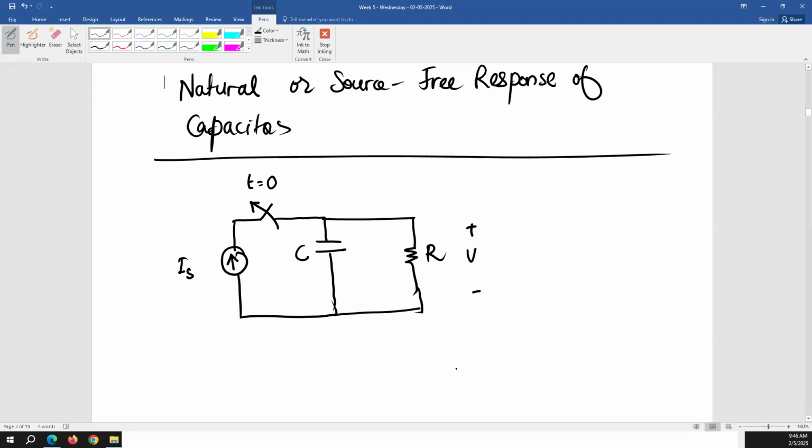So when we are analyzing these types of circuits, the first thing that we analyze, based upon the description that is given to you, is how long the circuit is running. If it is given that the circuit is running for a very long amount of time, basically that is to tell you that the capacitor is fully charged. And the first thing you are going to do is find what is the voltage across the capacitor when it is fully charged. That becomes your initial voltage on the capacitor that you are going to use when the capacitor is going to start acting as a source.